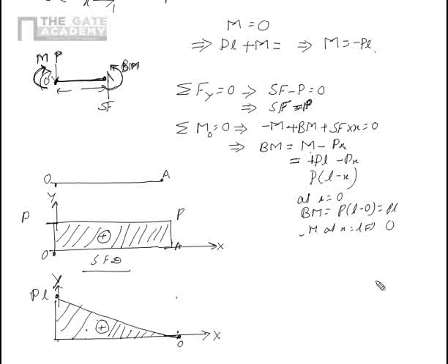So you see, it gives a lot of insight into how the bending moment and shear force diagrams work for a particular type of beam and a particular type of configuration of the beam. This configuration of the beam is a cantilever beam. So over here, the shear force and bending moment diagrams vary like this, which means that they look like this. The shear force for a cantilever beam is a constant if the force applied is P.